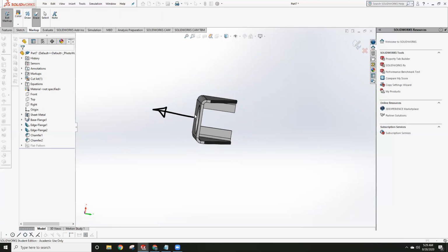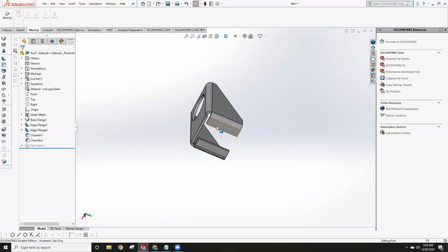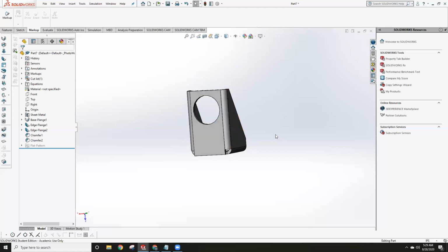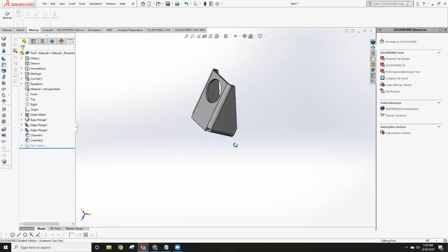But since it's not the regular L, it's reinforced, I don't know what to call this, it's not going to do that because it's mounted technically to the sides. That's pretty much what all this is. Sheet metal design is mostly just looking at how things are going to be supported and how to bend them and assemble them properly so that whatever forces you have aren't going to tear apart your pieces.